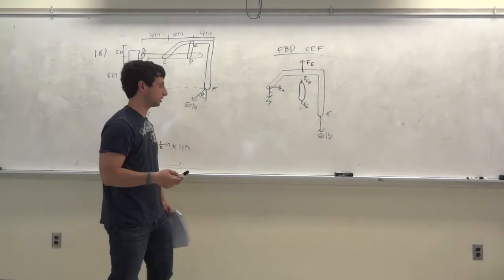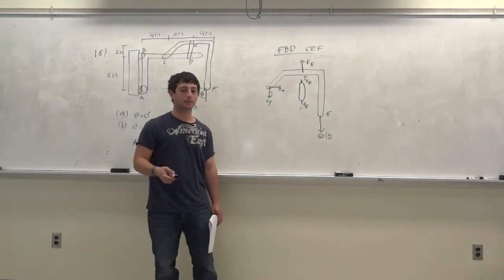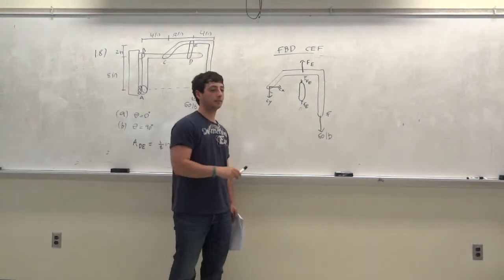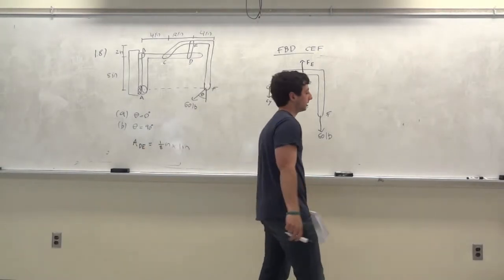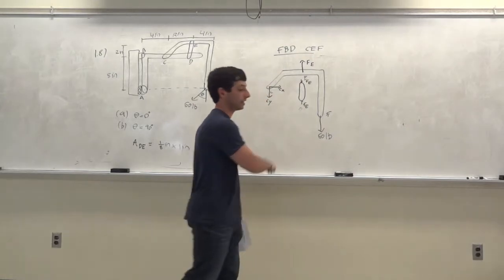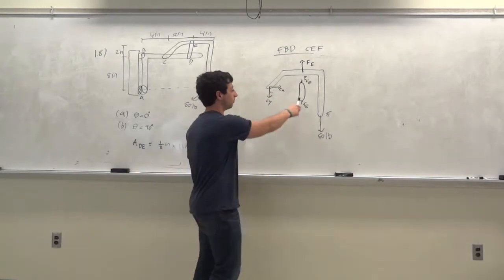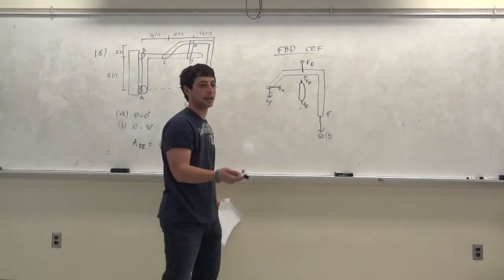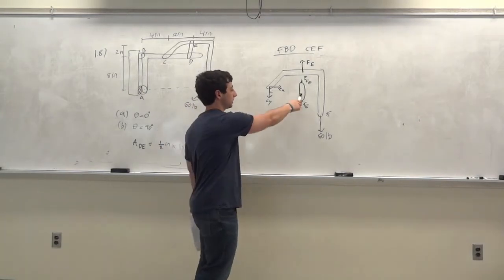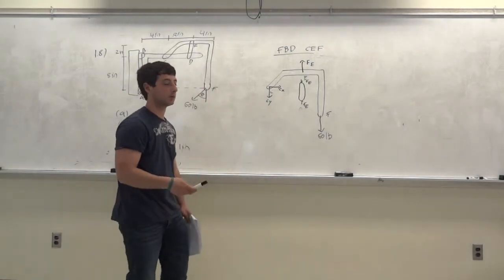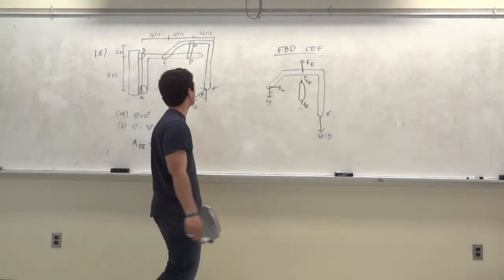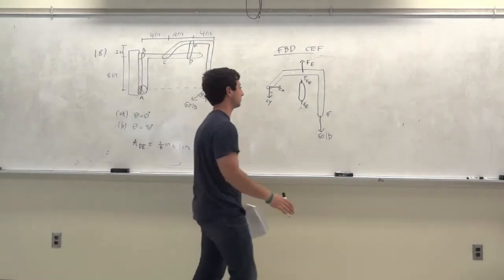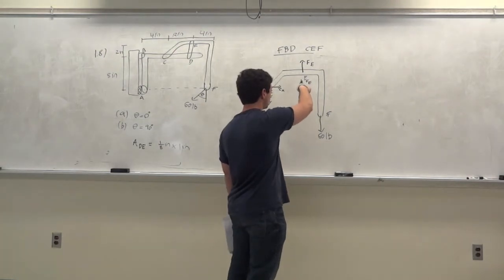So if we sum the forces in the x direction, what do we get? CX equals 0. So there is no CX. But that was good anyways. You could always figure that out from equilibrium, right? Why didn't I draw an x component in this member? What's special about this member? It's a two-force body. Two-force member, exactly. There's no x component. It's just along the member.